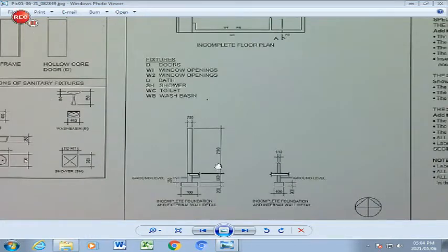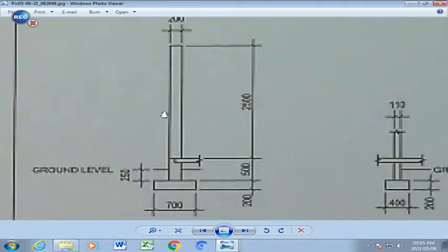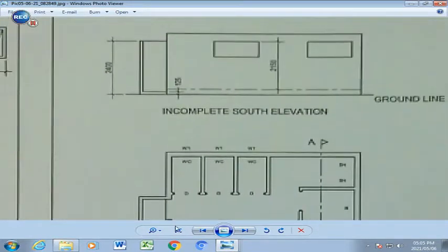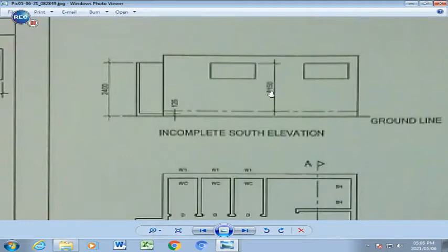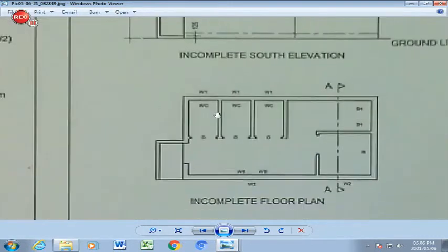If you want to know what it's going to look like, it is this construction that we see here. We have the foundation and the different floor levels, compacted hardcore and the concrete slab up until the ceiling level of that dimension over there, the wall being 200. All these dimensions must first be converted to a scale of 1:20 for you to be able to draw the detailed drawing. And only once you've done that, you may start with this drawing. Just keep in mind that the window is absent from this wall, so you have to put that in, and the window height is going to be this height that we see there, divided by 20, and of course the drop of the window will be that drop that you will see there, so that it fits perfectly into the wall.